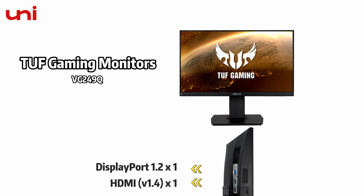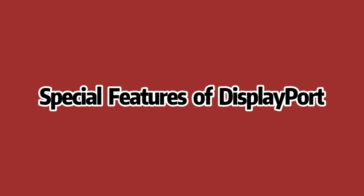Since the HDMI and DP both work at 144 Hz, 1080p on this monitor, you can choose both DP and HDMI cable. However, if you have an NVIDIA GPU, you'll need to use DP in order to use Adaptive Sync. Plus, you must make sure you are using the DP 1.2 cable or above version and HDMI 1.4 cable or above version.